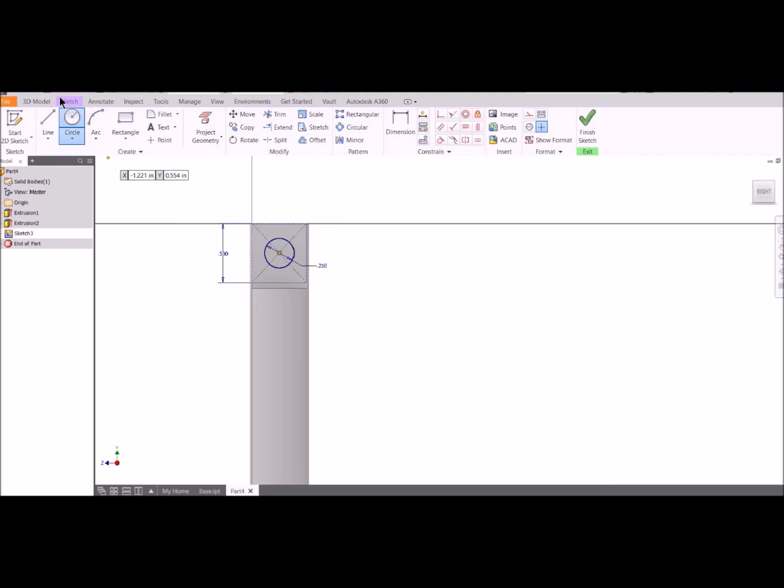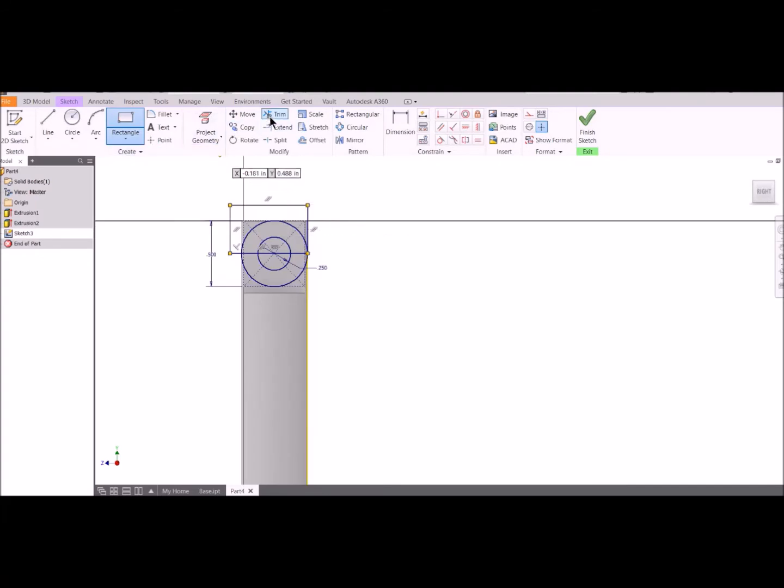Now, really, you don't want to make the dimensions exactly the same. There needs to be a little bit of tolerance in here, and again, that's something we can come back in the future and bump it out just a little bit bigger or smaller to make it fit well. I'm also going to round off the edges just so it has room to rotate in here. So I'm going to chop off these top 2 corners and chop out that middle.